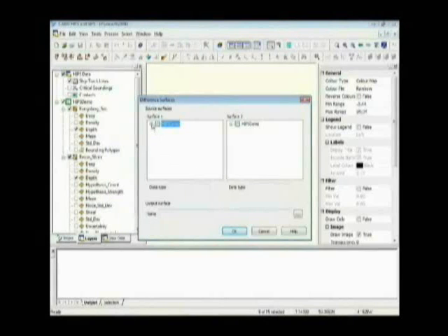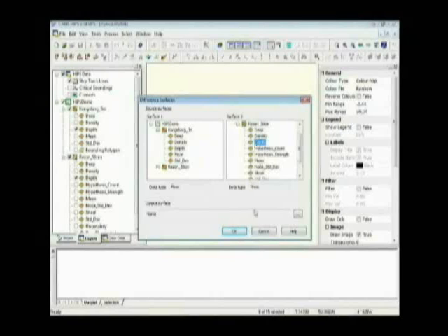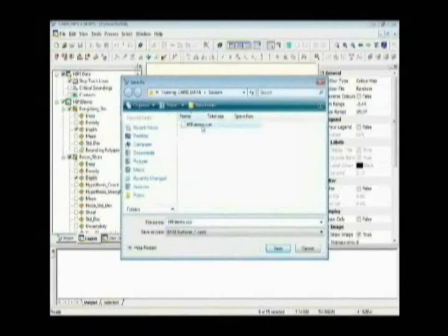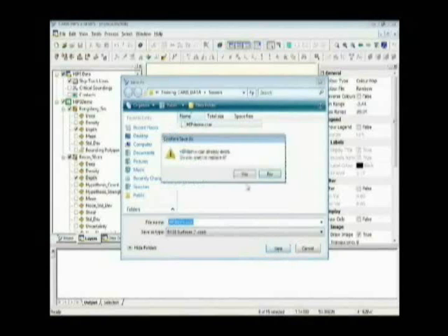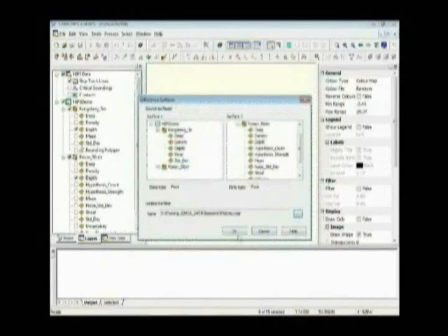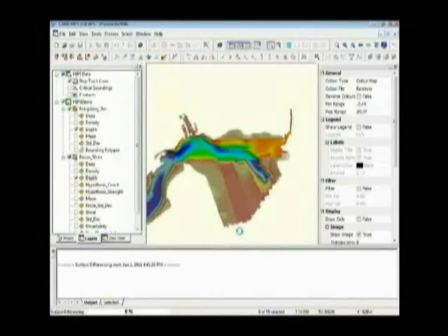Once you select different surface, what I'm going to do is select HIPS Demo, Kongsberg 3 meter, and the depth layer for the first, and then the Rezon 50 centimeter depth layer for the second. Then we need to put in an output surface name. I'm going to name it HIPS Demo, and just overwrite the one that I've already created. Yes, I do want to overwrite it, and then select OK. Once I select OK, it's actually going to start the creation process.